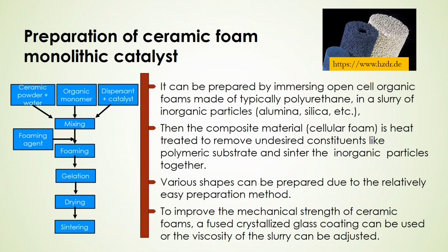There are several steps. First, you make a mixture of ceramic powder with water, that is, a slurry system, with organic monomer, a dispersant, plus catalyst particles.